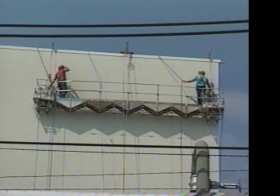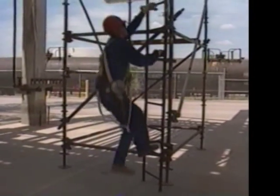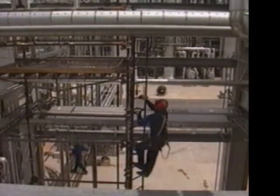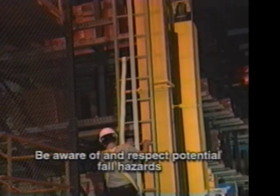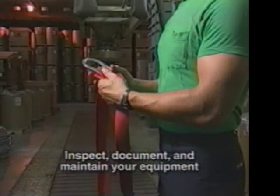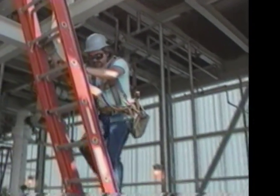The type of personal fall arrest system that is selected should match the work environment. For example, you may need a different system if chemicals, dirt, moisture, oil, or grease are present. If you face any of these situations, ask your supervisor. Be aware of and respect potential fall hazards. Properly use the personal fall protection equipment provided, and always inspect, document, and maintain your equipment to ensure its reliability. You cannot defy the law of gravity, but you can choose how you come down.